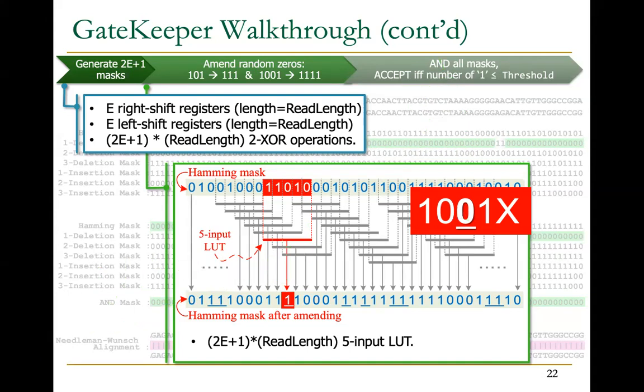Okay, let's delete the annotation and move on. So now the other case is to not have the don't care at the end, but to have it in the beginning, as in this. So to have this pattern as well. That is also accepted within a 5-input lookup table.